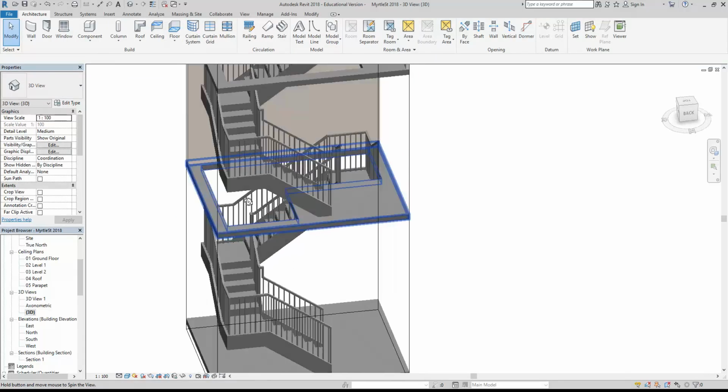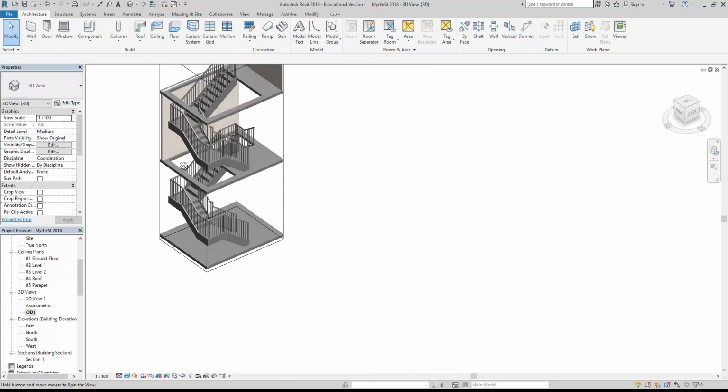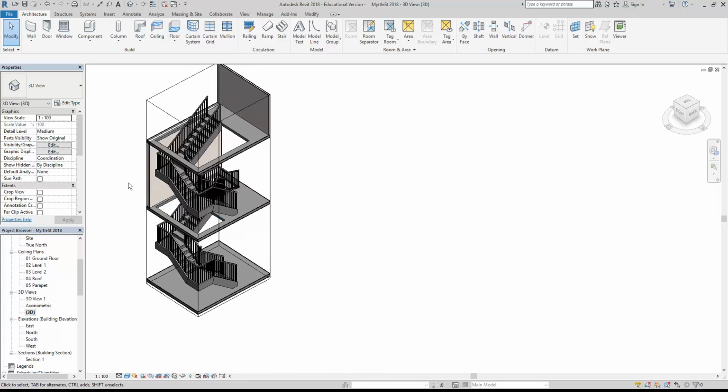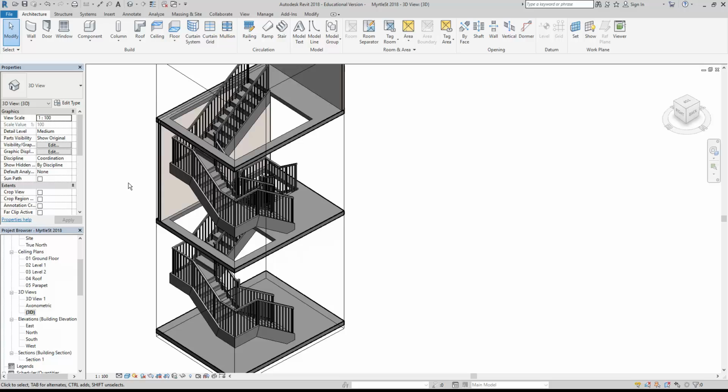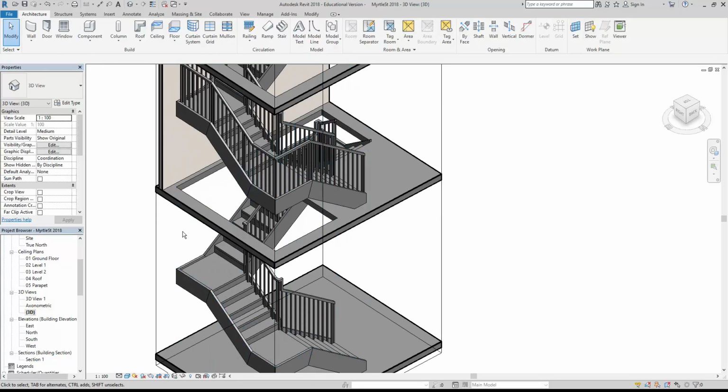But start with the basic one, the assembled stair. And that's what we've been doing. So that should work. After you've drawn the stair, it might be easier to come back and put the walls in afterwards. And then we would remove the radius. Yes, some of them though. Normally, that's right, and I'll just show you that as well. When you select a railing, you can delete it without deleting all of the stair. That would be fine in many cases, but here we want to just take parts of it out, so I'll have to show you how to do that.